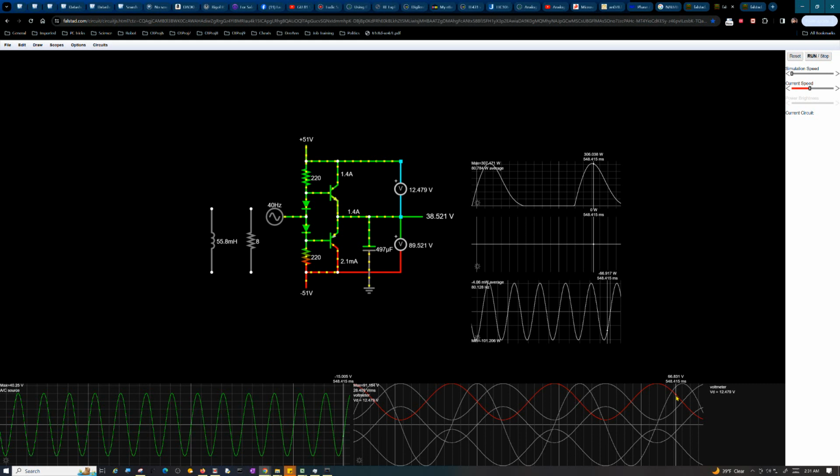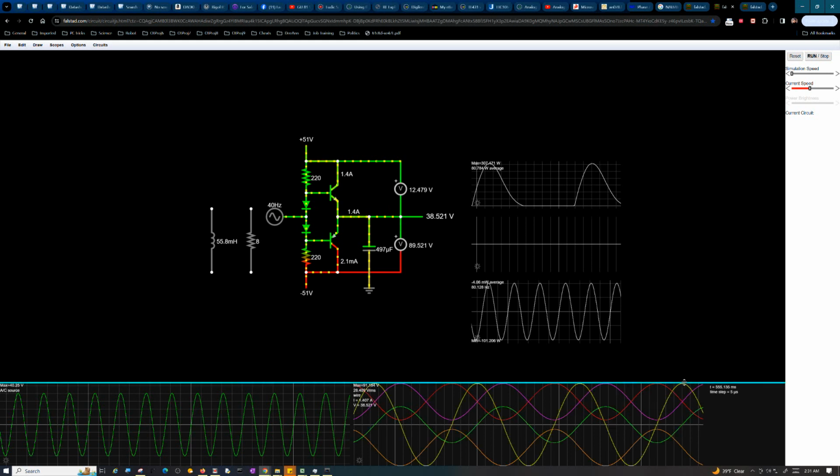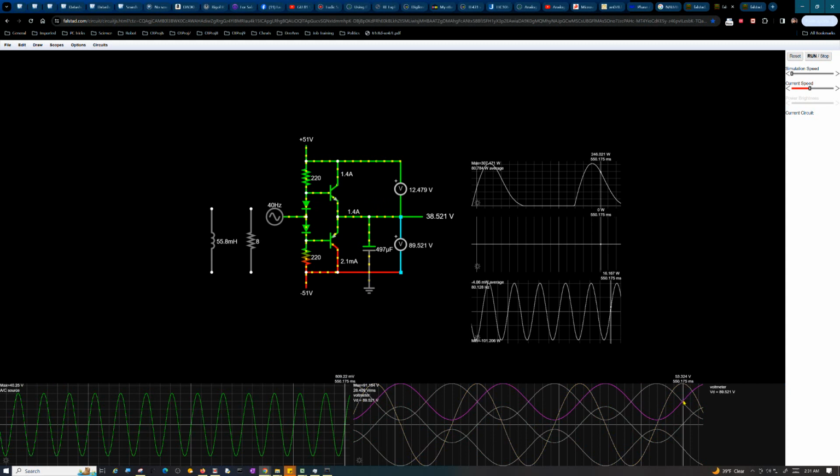Peak power is actually occurring when the voltage across this thing is about, what is it, 60, 68 volts or something, but it's certainly not full voltage. It's close to what he was sort of saying, but certainly even 51 volts is off a little bit, but it's certainly not peak current, because peak current occurs here, okay, we're at 5 amps, but the voltage drop across the system is about 50 volts at that. So that's true, but that's not its actual peak power point. Its peak power point is a little bit over here.